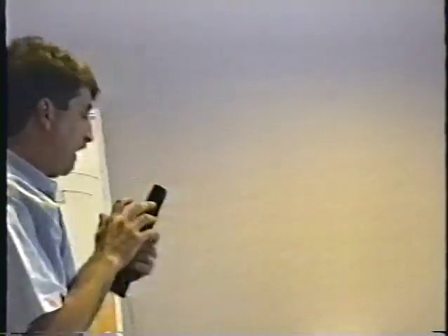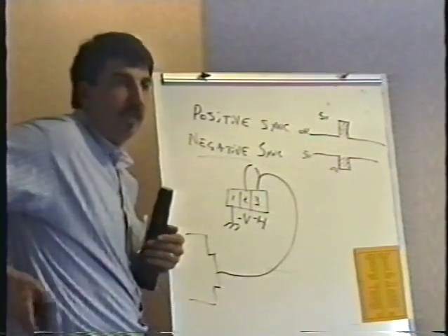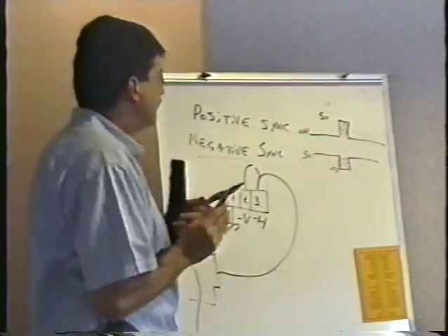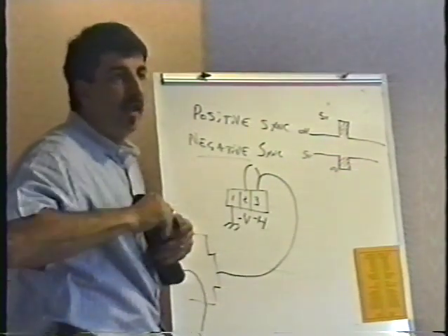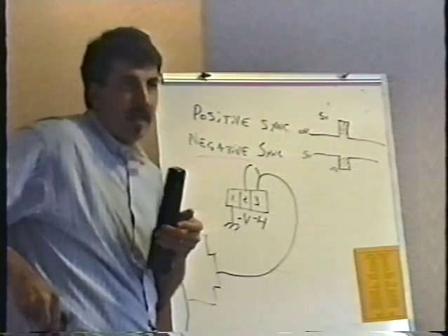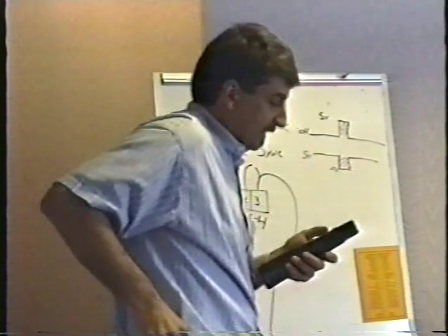Usually you can go way to one side before it starts to break. You go way to the other side, it goes the other direction, and you put it somewhere in the middle. Well, what I notice is I've got no range. I can just barely move that before it starts to break. I look over here, the jumper's in place. I take the thing out, I snip the jumper, point like this, solid as a rock. And now I have the complete range that I'm looking for. I can adjust it quite a bit either direction. So the point I'm making is this.